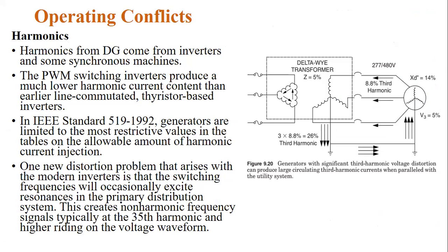There are different techniques to calculate harmonics, total harmonic distortion, total demand distortion, and so on. Harmonics are the waveform components at frequencies higher than the fundamental. The fundamental frequency is 50 Hz, the normal frequency. Anything more than 50 Hz we can call harmonics, and the order we can measure as 1, 2, 3, and so on.